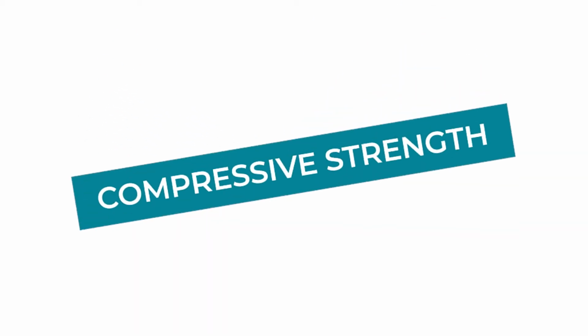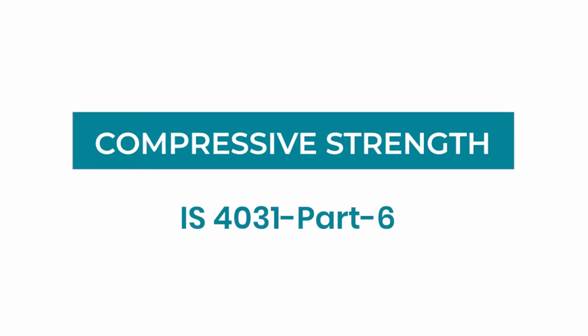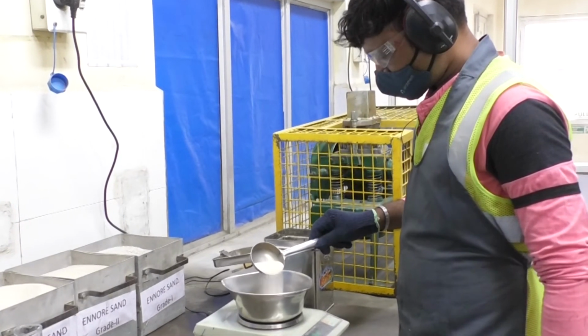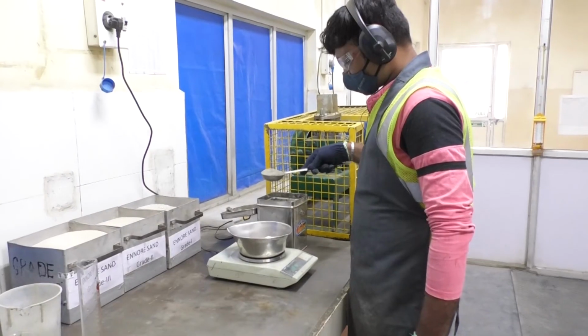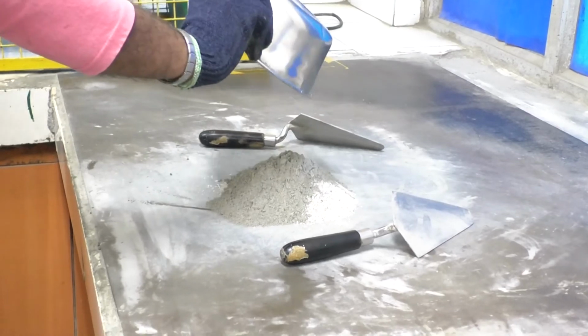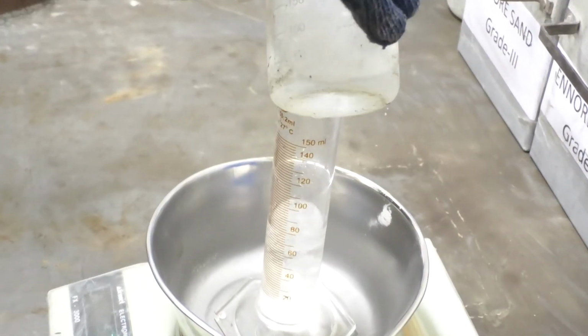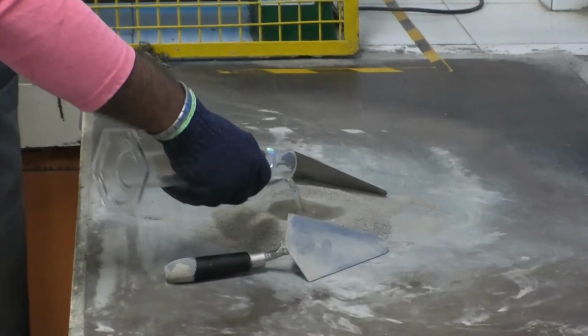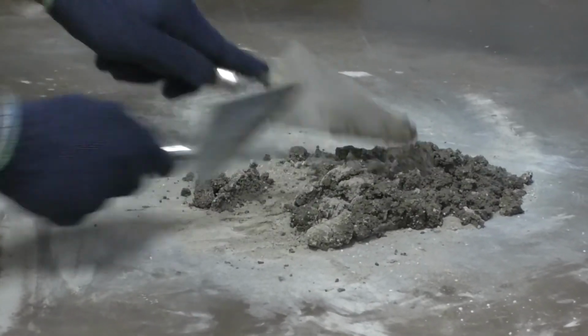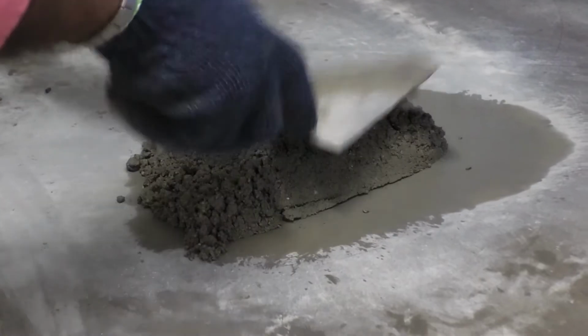Compressive strength. This test is performed as per IS 4031 Part 6. Take 200 gram of cement sample and add 3 types of standard sand, 200 gram each. Mix it well with gauging trowels for 1 minute. Then add the calculated quantity of water and mix it well with gauging trowels for 3 to 4 minutes, as you can see in the video.